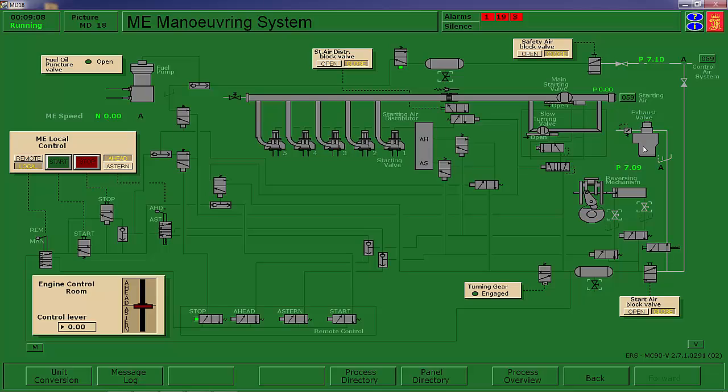If you were to put the main lube oil system on without having spring air on, the exhaust valves are already fully extended, and by adding more pressure onto that fully extended valve mechanism, you can over travel it and cause damage. So that, I thought, was an important concept that was built into this simulation. So put your spring air on prior to startup of the lube oil system.